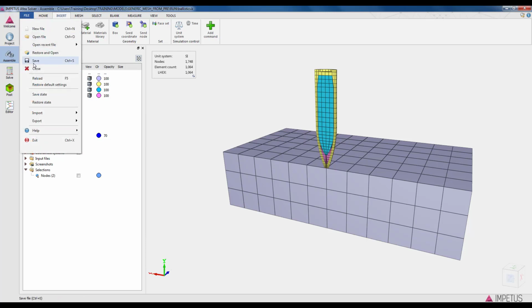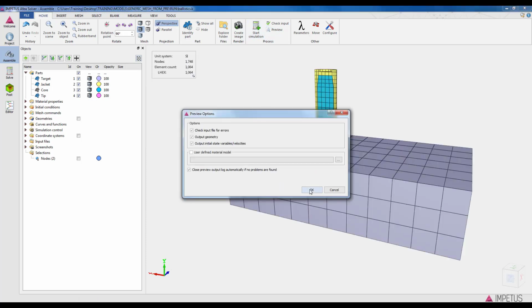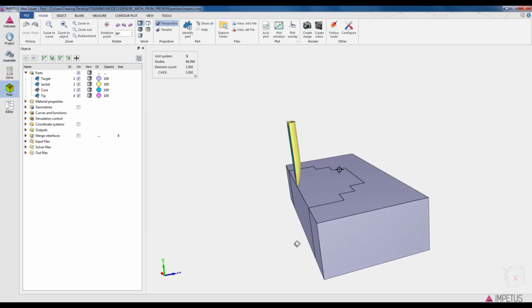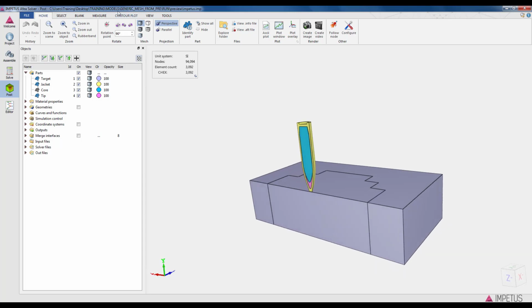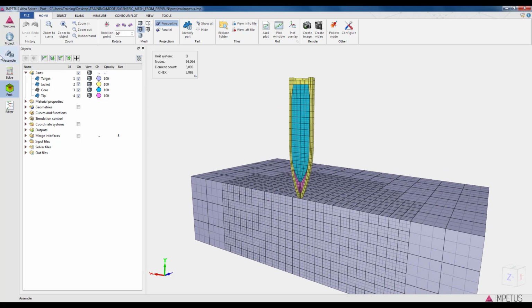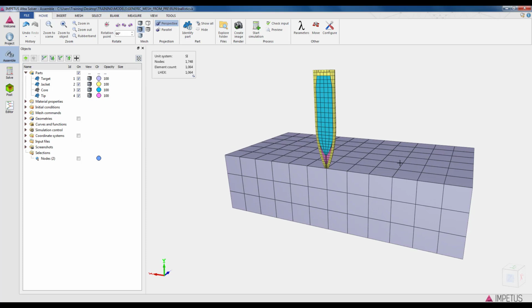Again, we can't see this one here. Let's just go and save this file and go to preview, and we'll see if we get the mesh that we're expecting. You can see now that something has definitely changed here. And yes, we got a much finer mesh here. Let's go back and continue here, because now we need to have some boundary condition. Now we basically have done the things with the mesh and the materials and the parts and simulation time, etc. So let's continue to boundary condition.